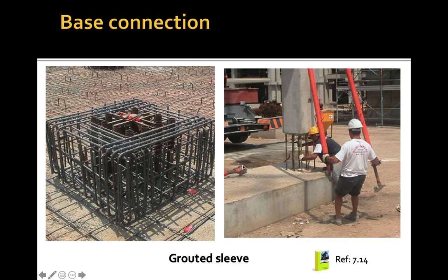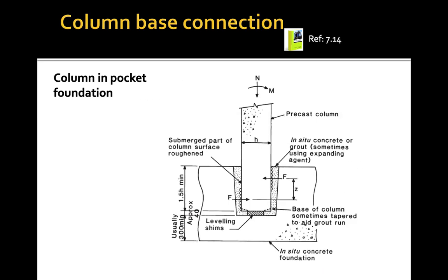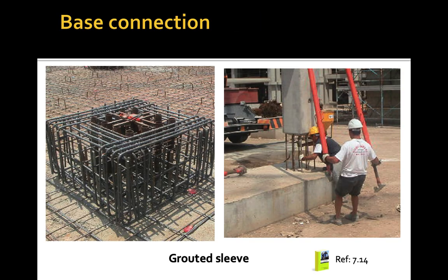This will be the last one for the base connection. As you can see just now, we have three types of connection from the column to the base: the grouted sleeve, the base plate, and the column in pocket foundation.